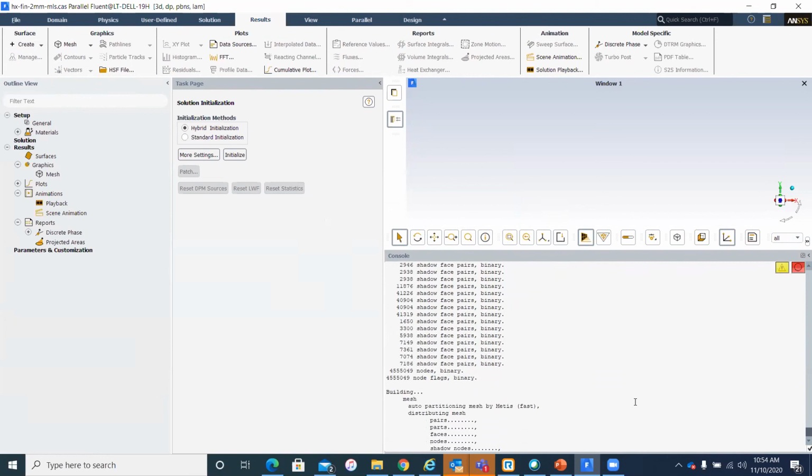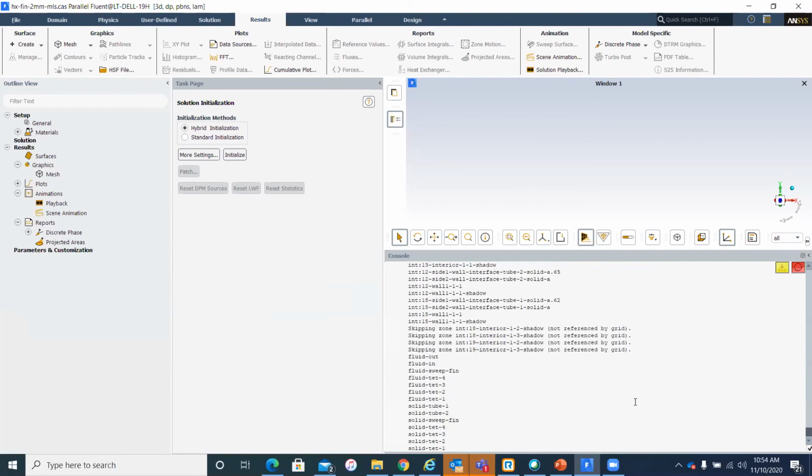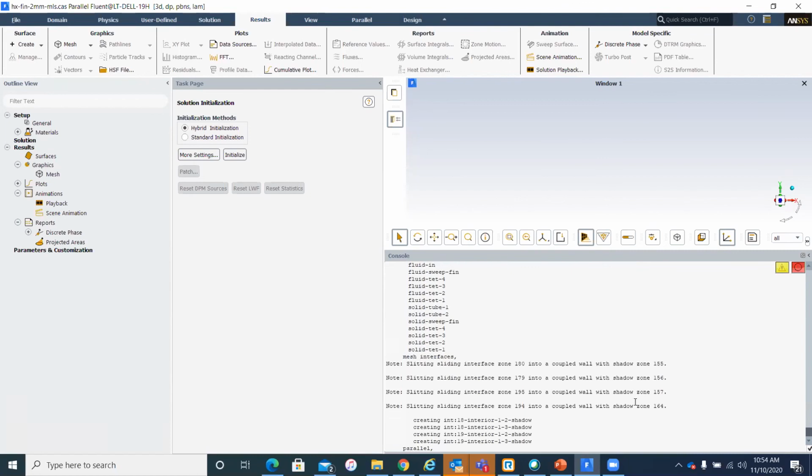And my recommendation is, if you're using CFD results to compare with established results from a paper per se, then make sure that your reference value in Fluent is the same as the reference value in your experimental paper. Otherwise, you may find that the results vary, and that will just cause unnecessary doubt.